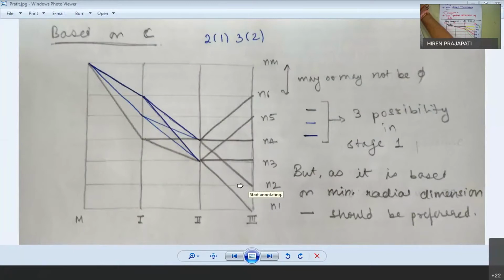Now we are not more interested in reduction in the diameter of the shaft, right? So we get maximum reduction in the radial dimension where we consider this node point at the mid of maximum speed and minimum speed, right? At that time we get maximum reduction in the radial dimension. Otherwise, if you shift this point down, then the increase in speed is with progression 5 raised to 3 and the reduction in speed with progression 5 raised to 1. So again, that increase in speed requires more radial dimension. So this is the midway where we get maximum reduction.